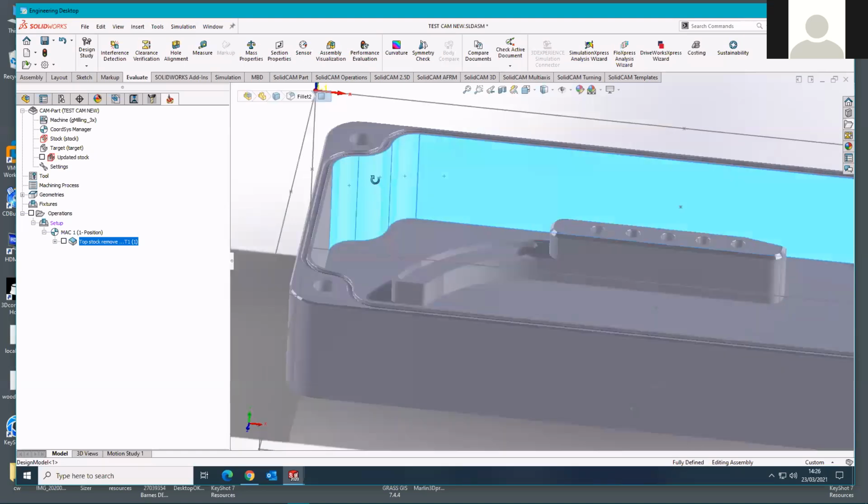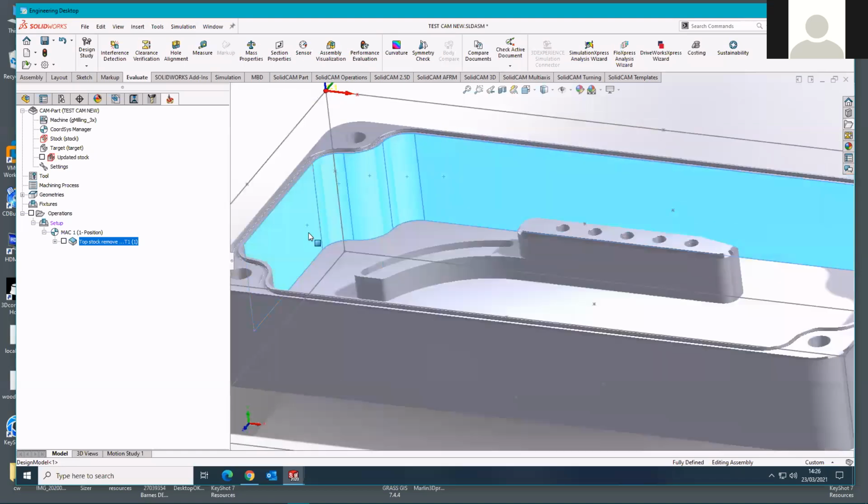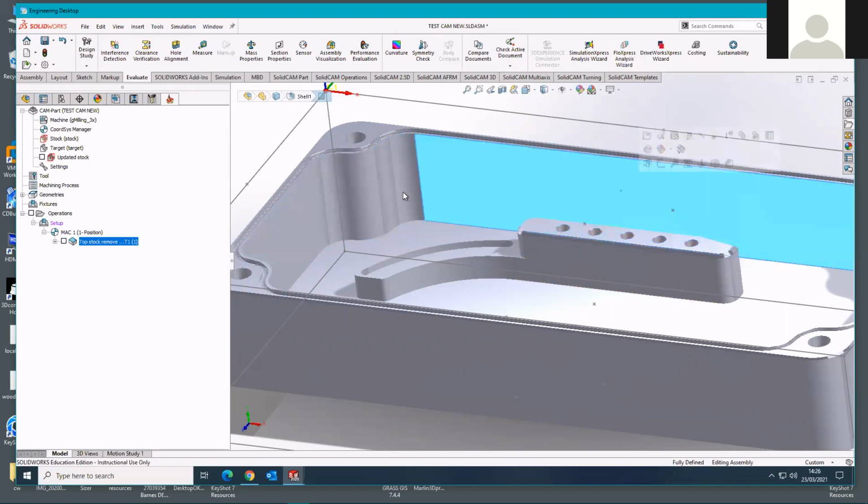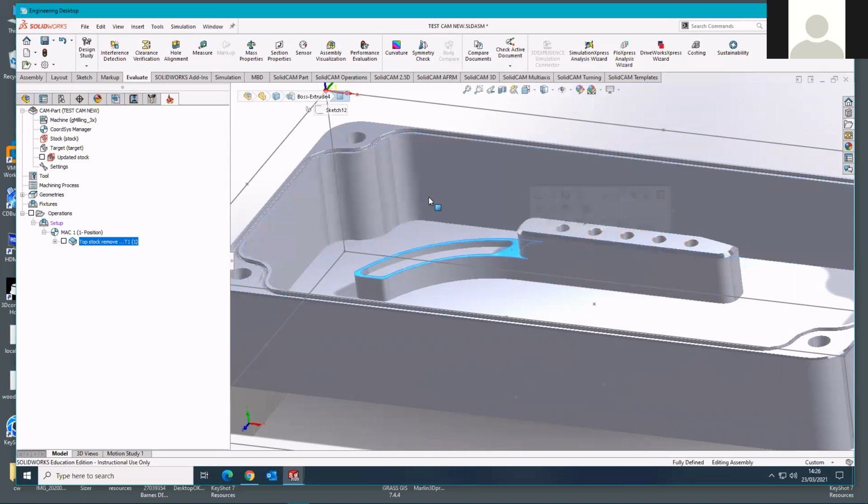And the reason for that is, if we machined all the way up to these walls at each of these varying levels, so if we machined all the way out to that wall when we were doing the pocketing up at that level, and then we machined all the way out to those walls when we were doing the pocketing up at that level, you would get what's known as a slight witness line. You'd be able to see the different levels that we'd machined to.